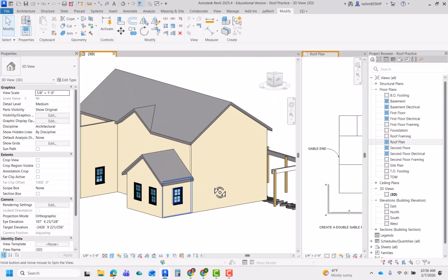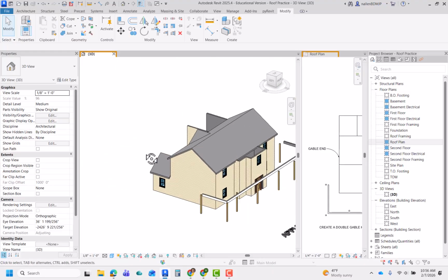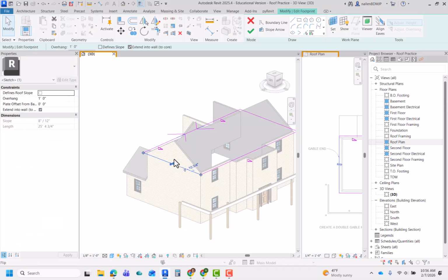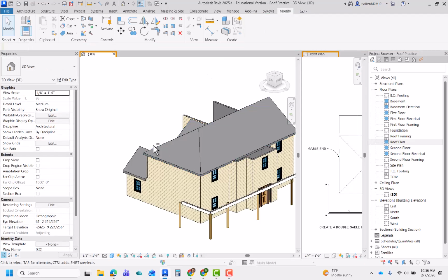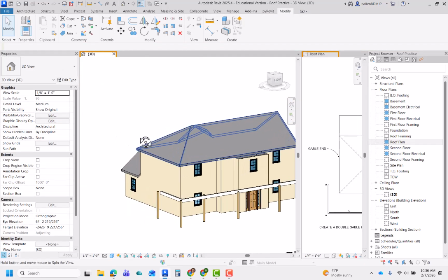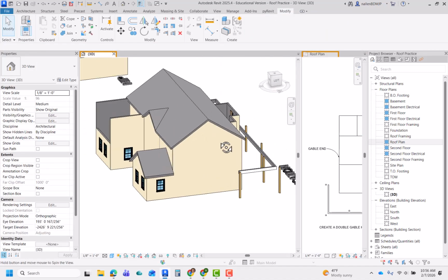That's great. Okay, the last thing that I want to mention before I end this video is that maybe you end up doing a house at some point that's like this. You're trying to start off with simplicity, but you don't have any gable ends. All you have to do is add slope on these ends, and you have a hip. So switching back and forth between a hip and a gable is really simple. You can look at your application, see what you need, and make it work either way.